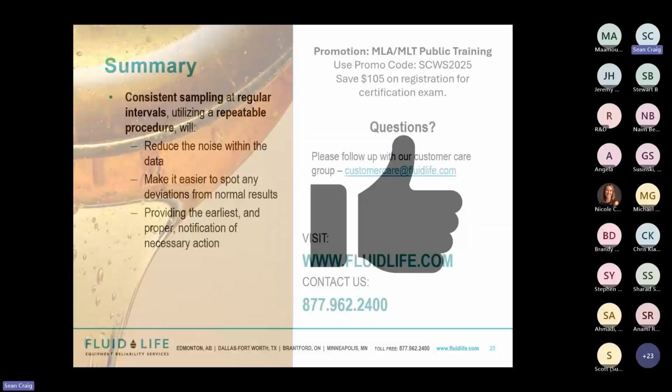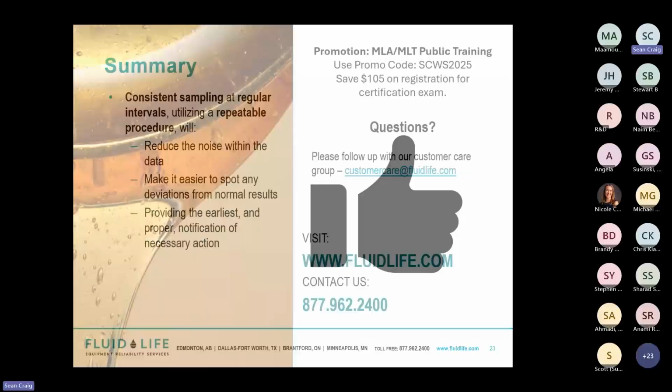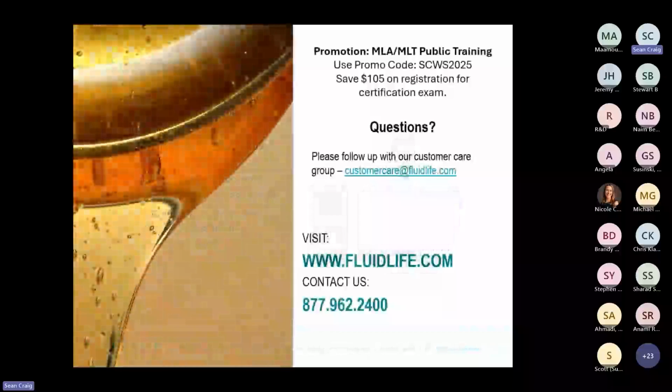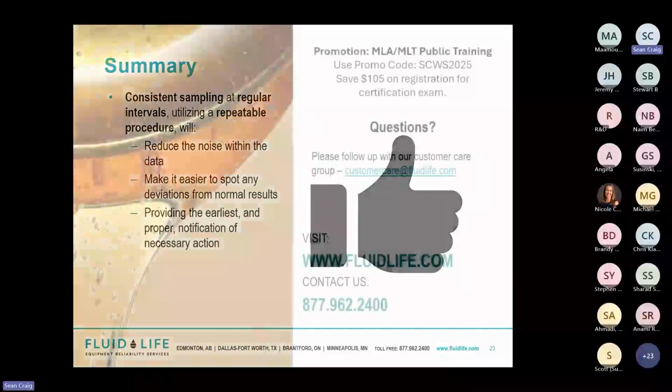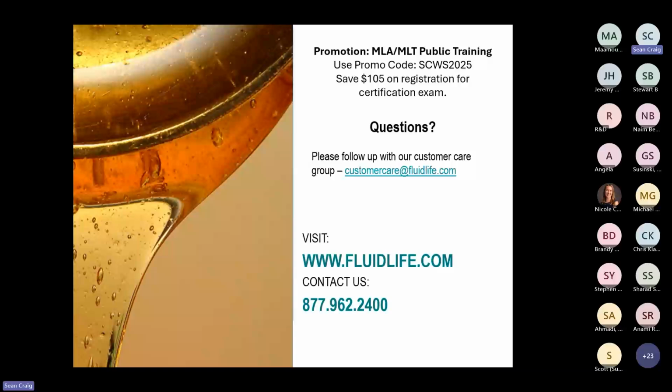So, I think I went through that there. So to wrap it up, when monitoring fixed gearboxes, pardon me guys, it keeps jumping away from my slide. When monitoring these systems, sampling at regular intervals using steady state is the best way. Sampling when it's hot and warm is usually the most advantageous thing you could do for your program to get a good view of things.